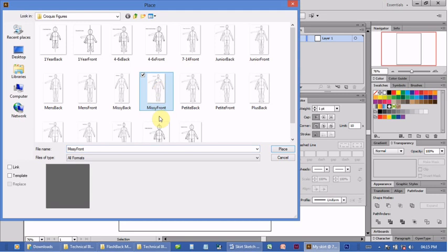So I'm going to select it first, and before I actually place it, what you want to do is make sure that these two boxes here are unchecked. Template, we're going to create our own template layer with our croquis layer. This automatically generates a template for you. We want to apply our own settings, so we're not going to check that.